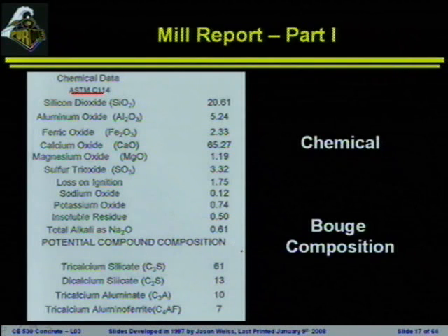They'll also typically go through and do the Bogue calculation for you directly, which is shown right down here, so you can get an indication of the four main compounds that we were talking about earlier. Our calcium silicates, which are the top two, and then our C3A and our C4AF.